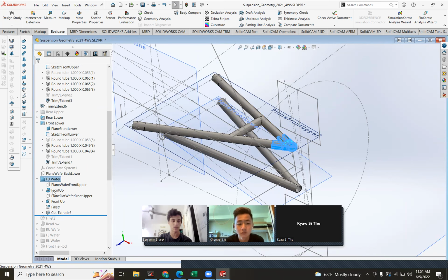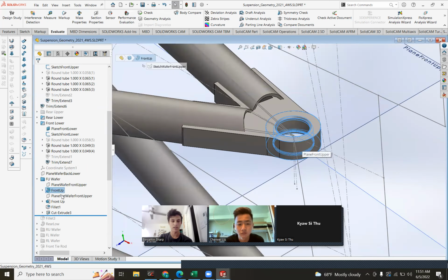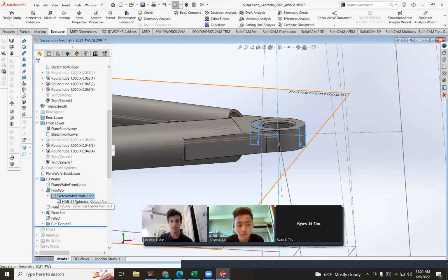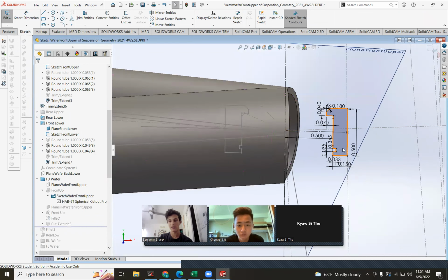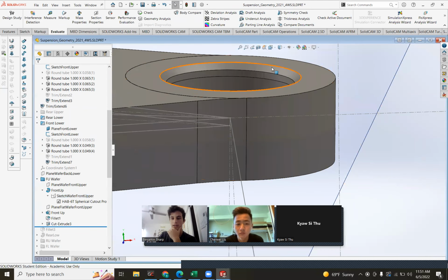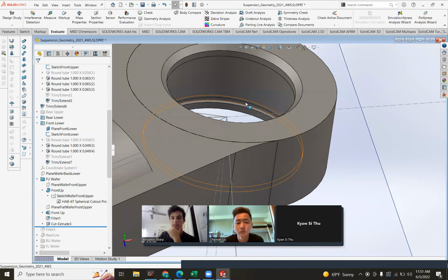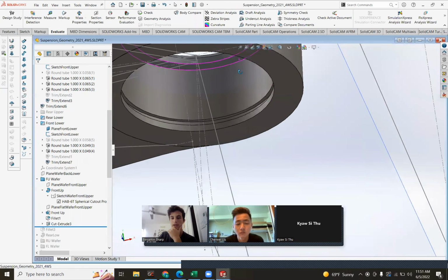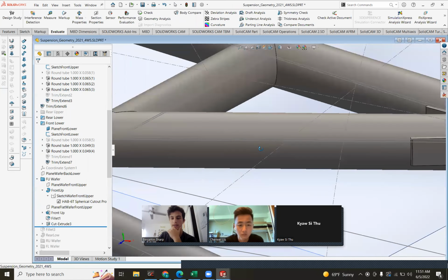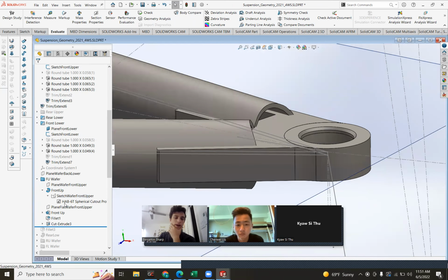Right before this point, it looks like just tubes. But then I create this revolve feature right here. This is another sketch block. You'll want to copy this exactly, to the fraction of an inch. It's kind of weird to think of it in this shape, but this defines all of the material that you need around the spherical bearing, and then you revolve it, and it creates the cup with the retaining ring cut out and the lip on top and just enough material around the edge to keep the bearing seated well.